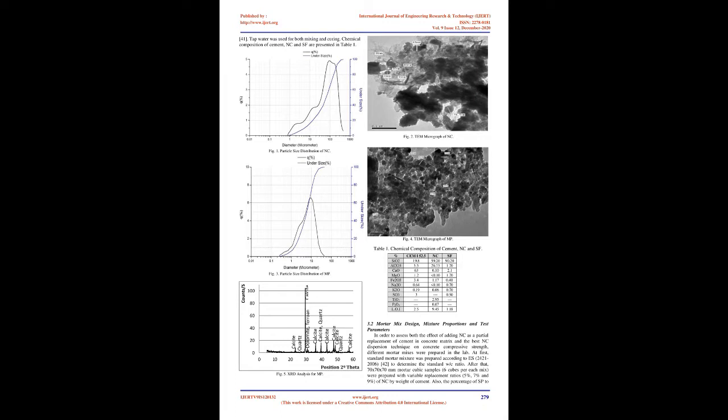It was noticed that the additions declined the workability of mixes due to agglomeration of metakaolin. The authors attributed that unfavorable situation to the increased demand for mixing water, resulted from the constant ratio of the superplasticizer used for all mixtures. However, incorporation of these powders in concrete improved strength and durability compared to normal concrete. The optimum percentage was 15% for both replacements of fine aggregate by weight.